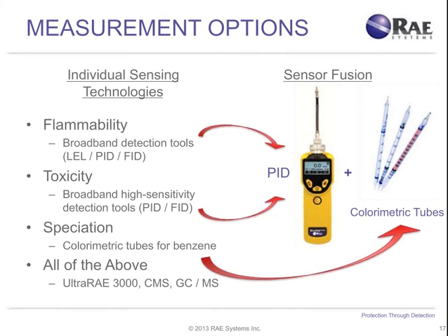You can also monitor at a very granular level, down to 50 parts per billion, in 50 parts per billion increments. But what we're looking at is less specific, less technical tools. Ease of use is something that is of importance for our discussion here. So you can use sensor fusion to use basic tools and detect benzene throughout its concentration range and in a specific fashion. So you can use a regular photoionization detector.